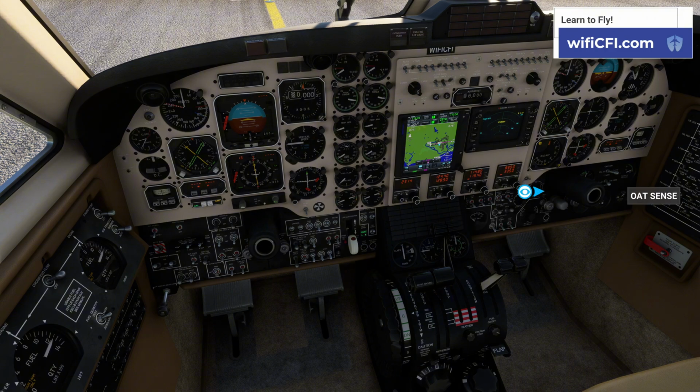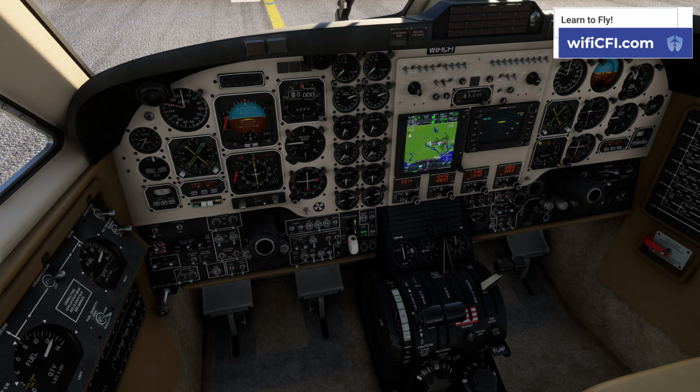While we're up here at this 1800 RPM, we can do our engine ice vanes check. So our ice vanes are closed right now. Turning them on should give us a little drop in torque since we lose some power. So if we get our left and right one on, it might be hard to see in the sim, but it is just a little drop on both the torques. And then we'll set these for takeoff. We do not need them for our takeoff today. And then we can go ahead and bring our power levers back to idle. Looking good, looking good. Flight and engine instruments look good.